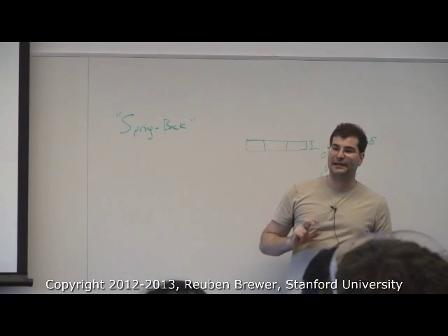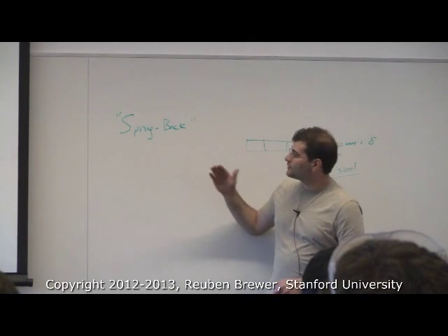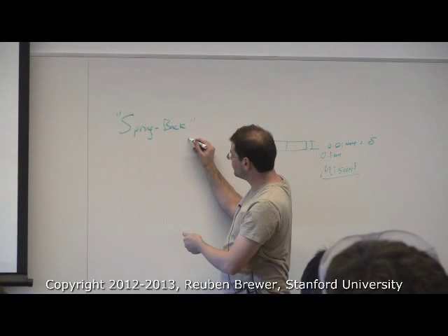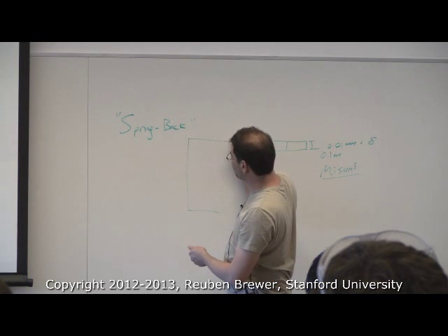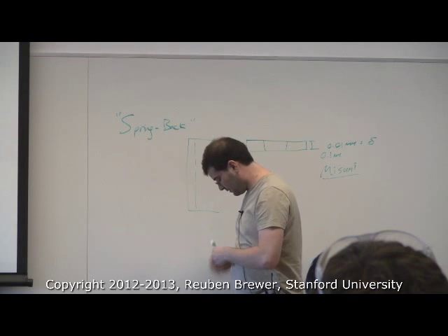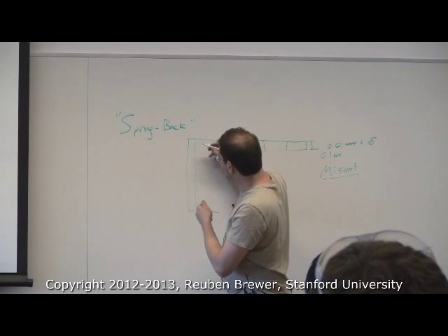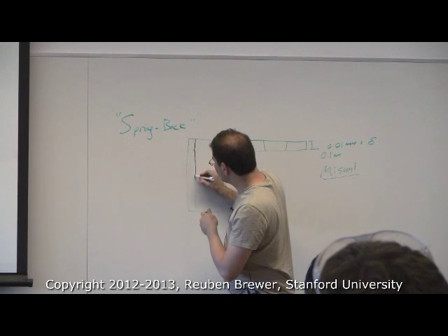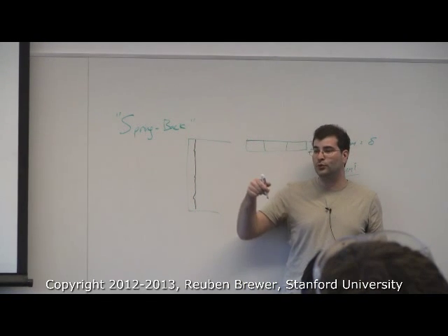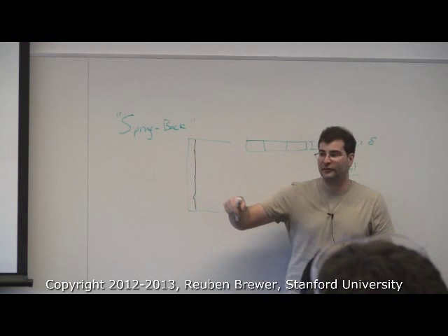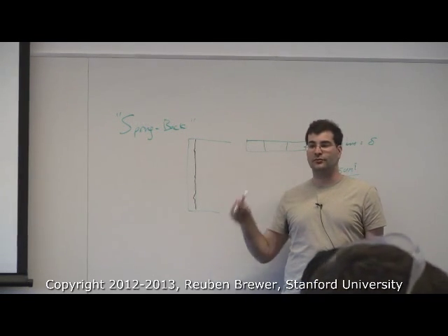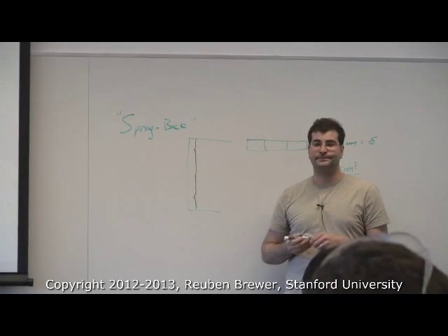Let's look at it this way: if I'm trying to take this chunk of material here and cut down here, if I zoom in with a different color, I'll have just a little bit that got left over. Some of it will be because the tool bent and went out of the way, and part of it, particularly in our case, is the material bent out of the way and then came back after we removed the reamer. So the second pass gets rid of that.